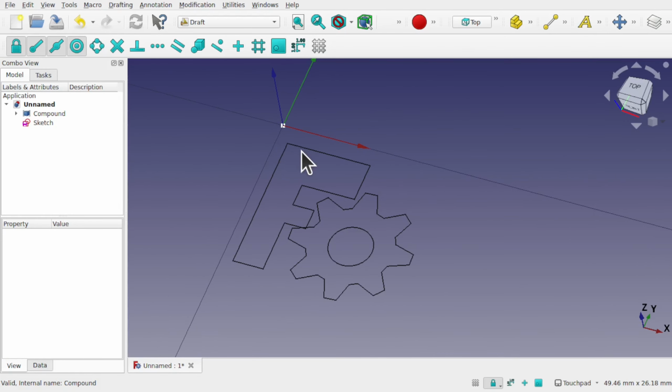So before we move this, we need to make sure our snapping is correctly set. If we look to the top, we have a number of snapping tools, and these may be shrunk down under a drop down with this padlock here, maybe over here somewhere. I've got my icons larger than normal so we can see what's going on. Make sure the snapping is checked and set on. This will mean that all these will be colored and become available. I want the snap endpoint, the snap midpoint, and the snap center point. Make sure these are checked and they have a gray background.